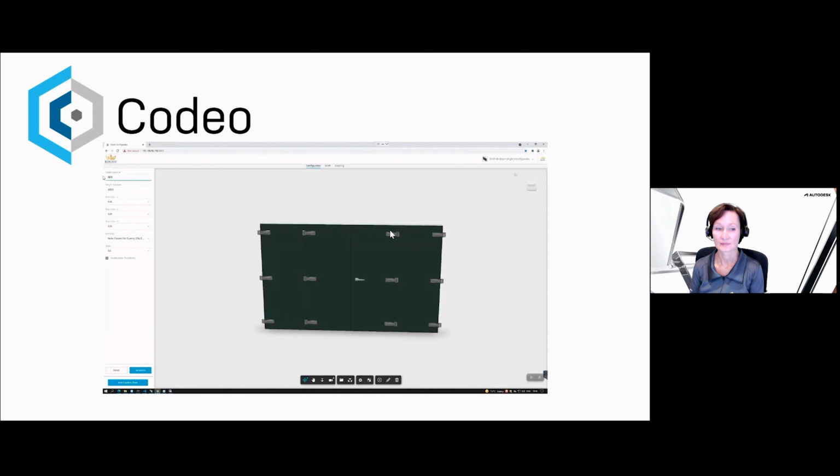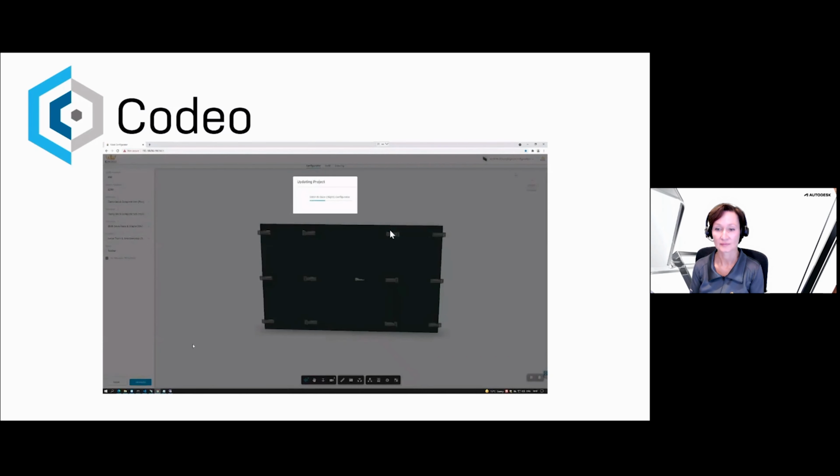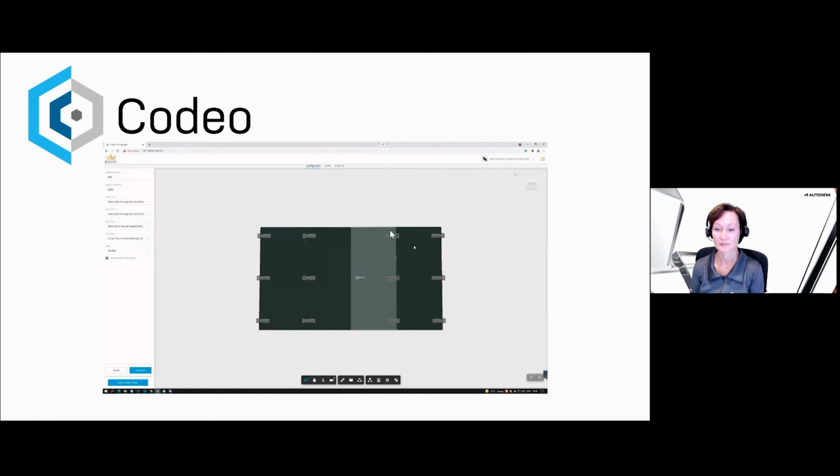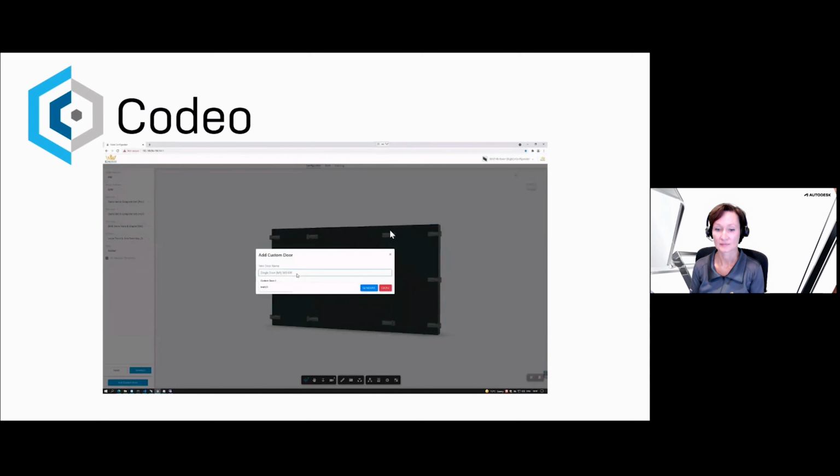Gonna change the door leaf width and height parameters and add lock options, select rubber seal and generate it. Done. I'm gonna apply the same process to add this custom door to the main configurator's wall list.